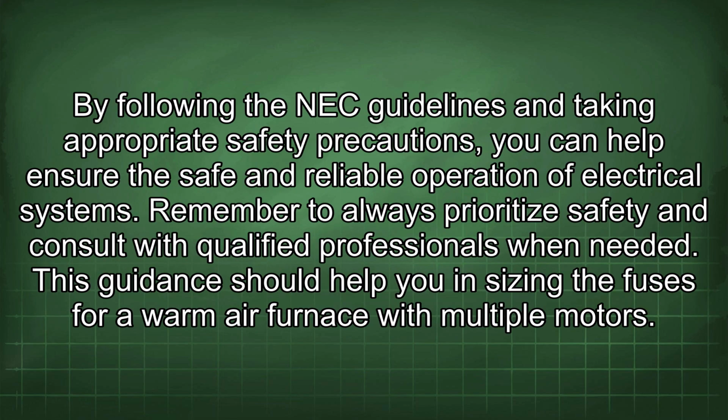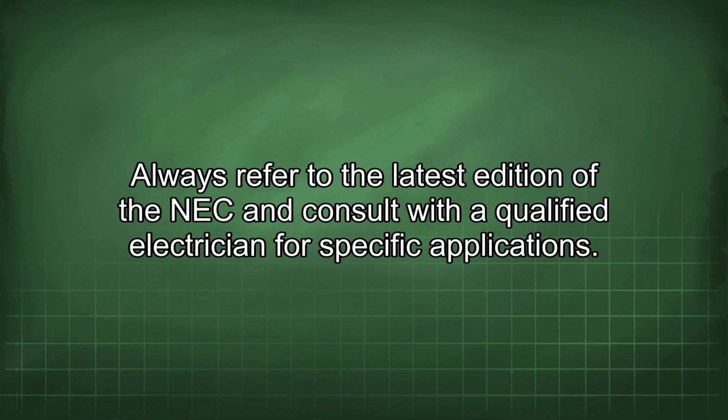By following the NEC guidelines and taking appropriate safety precautions, you can help ensure the safe and reliable operation of electrical systems. Remember to always prioritize safety and consult with qualified professionals when needed. This guidance should help you in sizing the fuses for a warm air furnace with multiple motors. Always refer to the latest edition of the NEC and consult with a qualified electrician for specific applications.